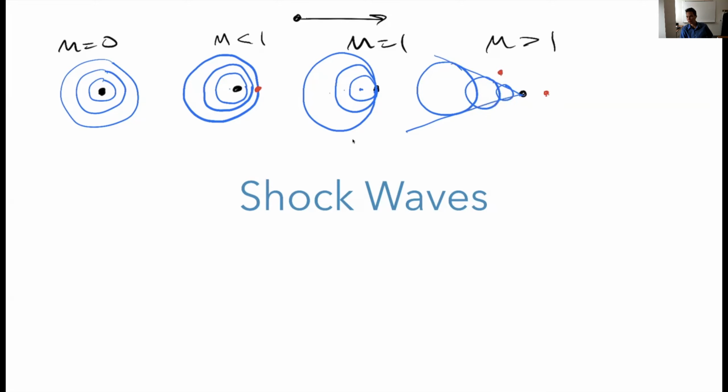Now a shock wave and a Mach wave are not exactly the same. We may talk about that a little bit more later, but conceptually it's a very similar idea. A Mach wave is actually an infinitely weak shock wave because these are just sound pressure levels, but for a stronger disturbance, we get a shock wave. It's going to have a steeper angle than this, actually. And through that shock wave, it's really like a boundary layer. It's not really instantaneous, but from an engineering or macro perspective, it is because it's a very, very thin, viscous layer where the pressure, density, temperature, and all the fluid properties change, and the direction of the fluid has to change effectively instantly.